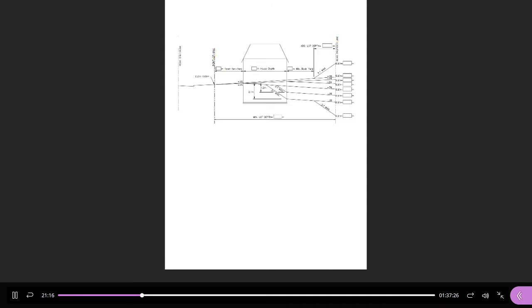So you're going to have an elevation at the front, and an elevation at the back. What you do in between is kind of spelled out in this cross section. Okay, so I'm going to assume an elevation here at the front. Let's say this is elevation 0. There are two different lot grading types. There's only two types. So here they are. I'm going to type in here. There are front draining, and there are split draining lots.